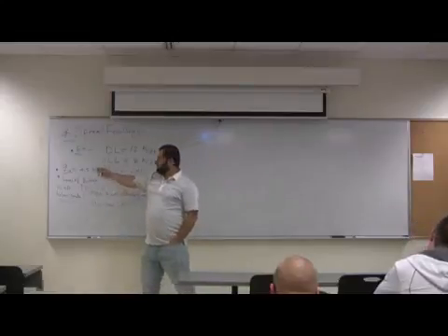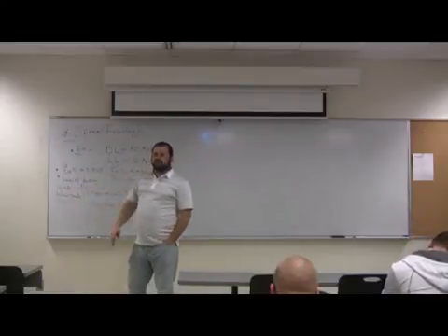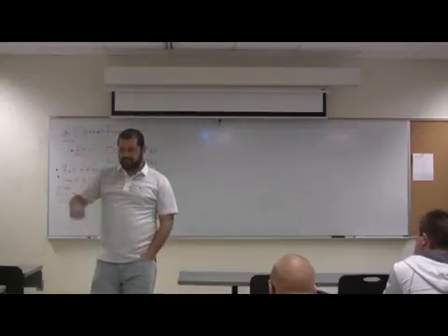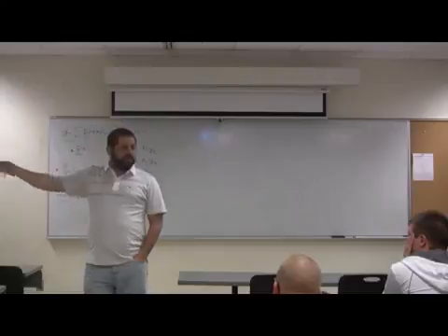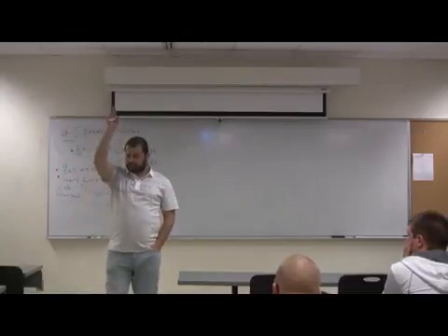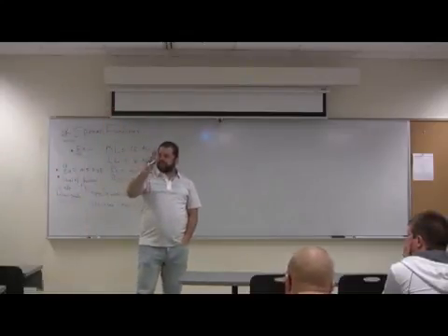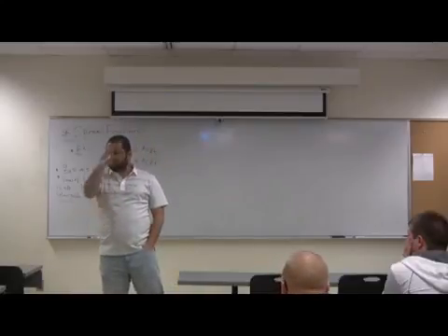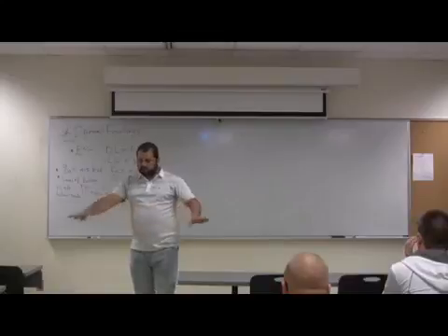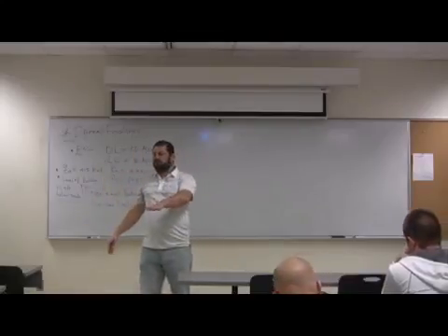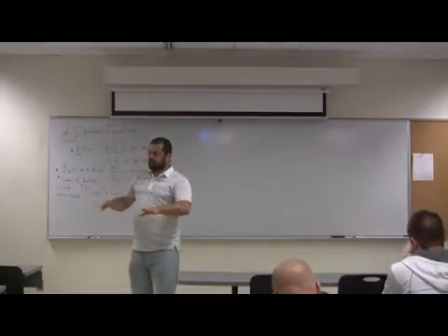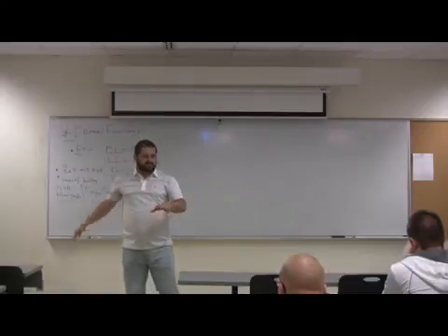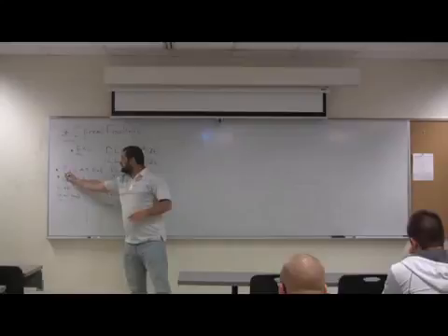So the Q allowable is the bearing capacity of the soil. You know where we get this from? From the geotechnical office. The guys go and they do the profile and they get whatever soil characteristic and they tell you the bearing capacity at 1 foot is that, 2 foot is that, 3 foot is that, and the type of the soil they have. Then they say, okay, this is a good foundation from the experience at 4 feet or 5 feet. There's that type of soil, rock, some good bearing capacity of that much. So this comes to the structural engineer from where?